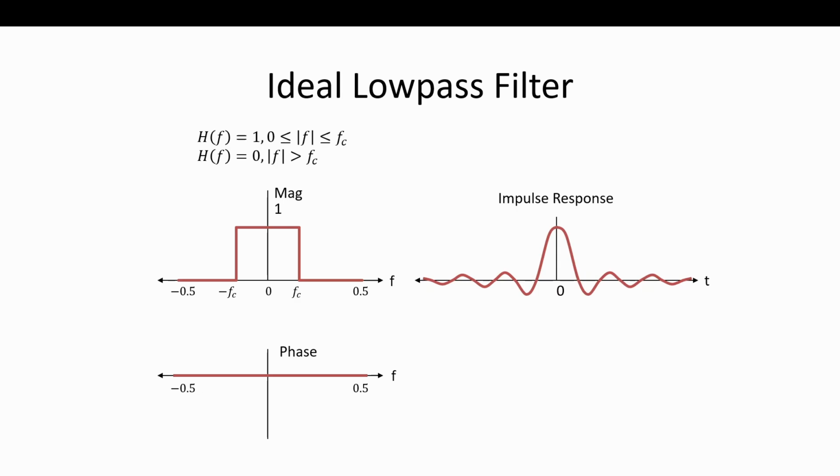So you're seeing the impulse response for a non-causal filter as a sinc function that has to go to plus or minus infinity. It's not only non-causal, it has to go for all time that was and all time that will be. And if you can do that, then you can make a brick wall filter, right? But we can't do that. So first step is we delay it, because Mr. Causal Police in the back there says we can't do it. So we delay it to make him happy.